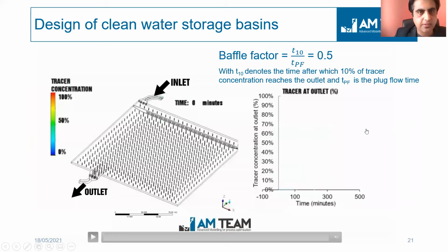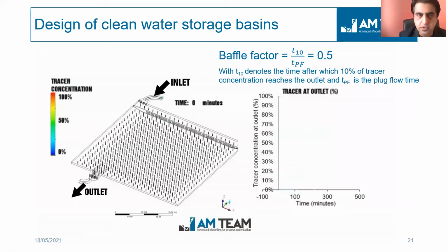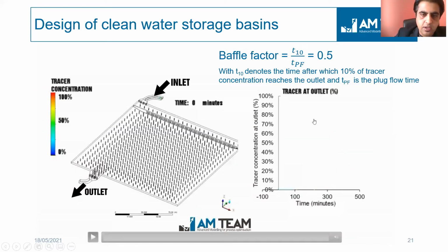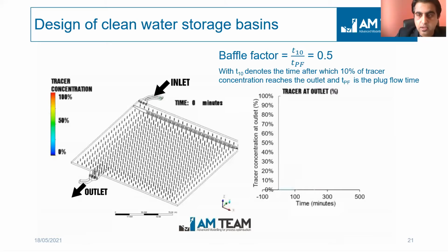So the first case is actually of clean water storage basins. So here on this slide, you see on the left side a CFD simulation, and on the right side, tracer concentration at the outlet of the basin. Why we have put this slide on the show is that normally this is a common practice in the industry. If you want to optimize the mixing in your basin, you would like to do a tracer test and see the concentration of tracer at the outlet, like really physically doing the tracer test and calculating baffle factors to evaluate the mixing.